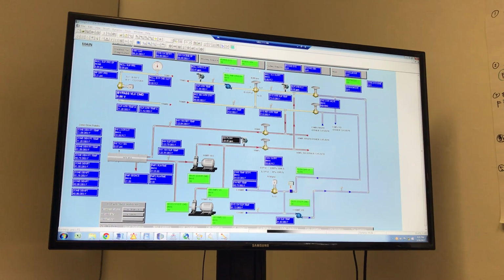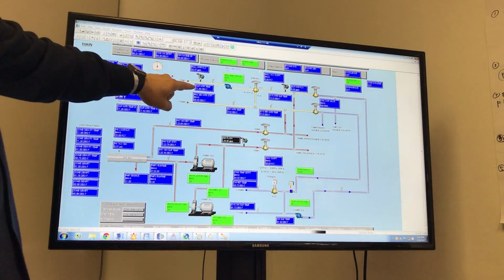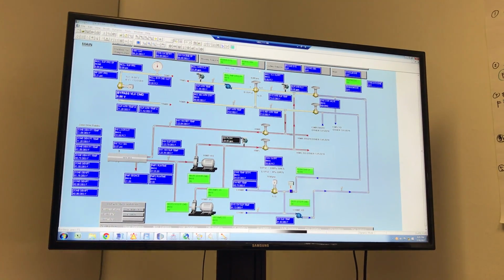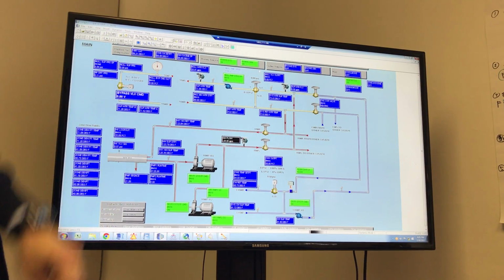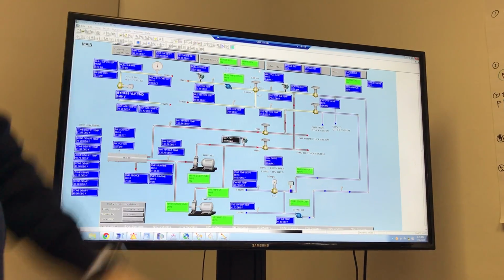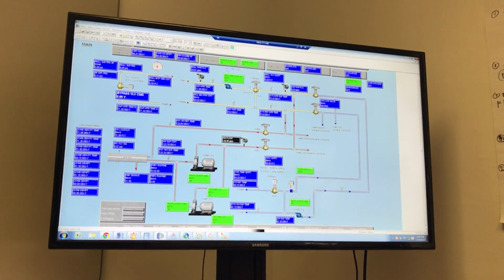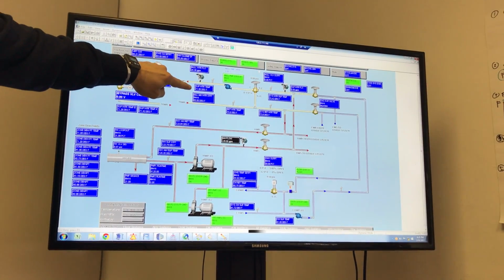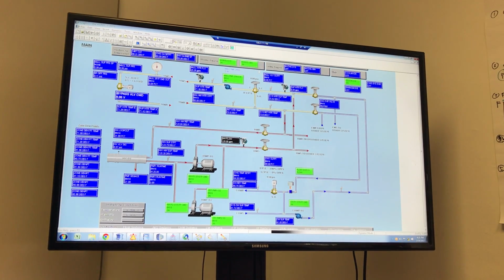So what's the supply water temperature right now? Supply water temperature is 71 degrees, and there's a set point for that, 80. So it's trying to meet the set point. Right now we are in heating mode because it is enabled and it's calling for heating. 71 doesn't make sense that it would be that low. It should raise to 80.